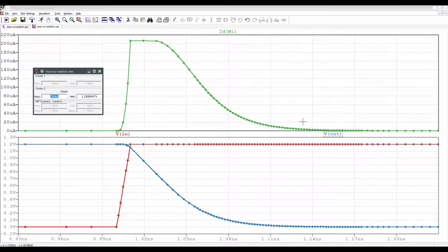If this is an RC circuit, these data points would actually be spread way out because it is a true first order differential equation that describes it. This is not a first order differential equation. Remember, it's really a quadratic, so the simulator really needs to say, hey, I need to do a good job and get lots of numbers here so I can be accurate.